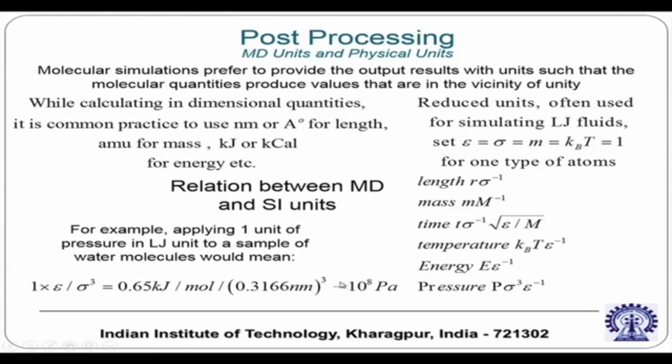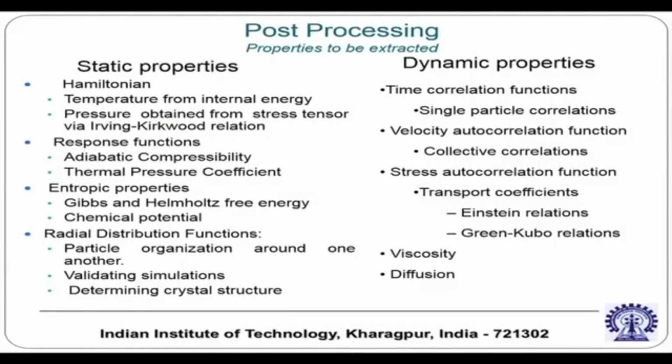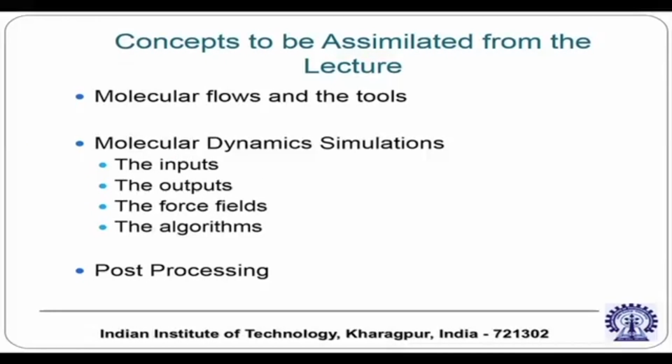So many times in molecular dynamics we say 1 unit of pressure, that will typically mean this kind of physical unit. So as an engineer we should be comfortable with converting from the reduced unit to the physical unit, because we are commonly asked to design a practical problem where the units are physical units and not just the Lennard-Jones or the reduced units. So you can post process the properties that you get from the molecular dynamics simulation. So some of the static properties and the dynamic properties, so you can post process a wide range of properties, I am not going into all this.